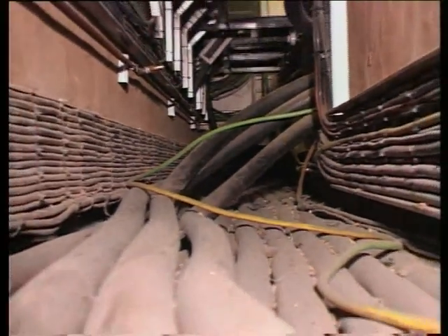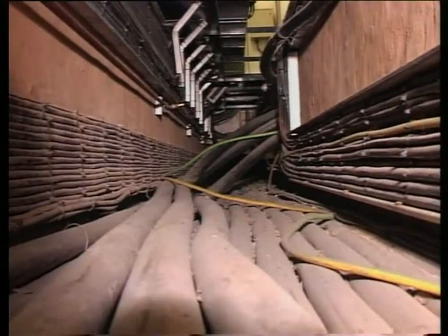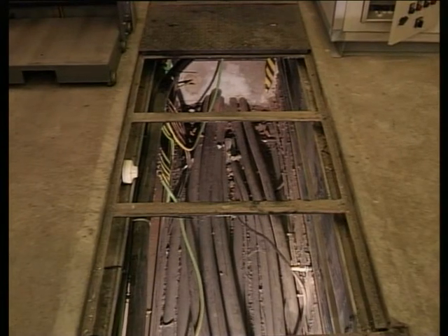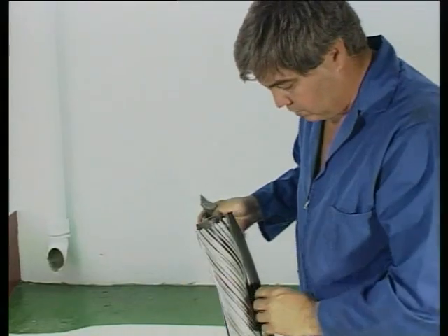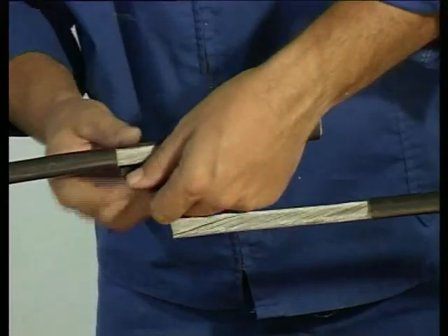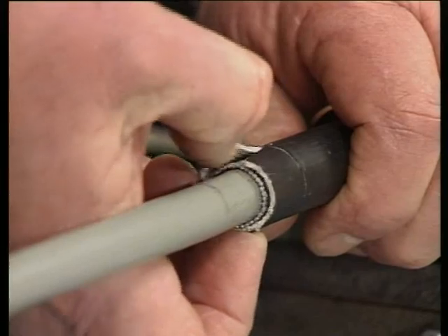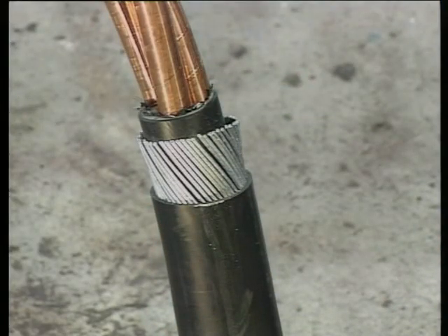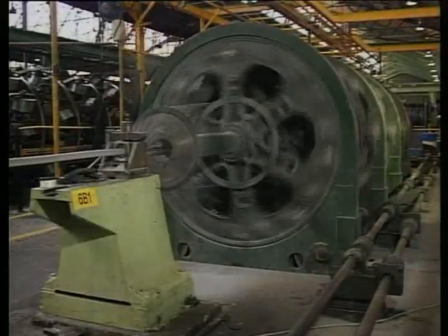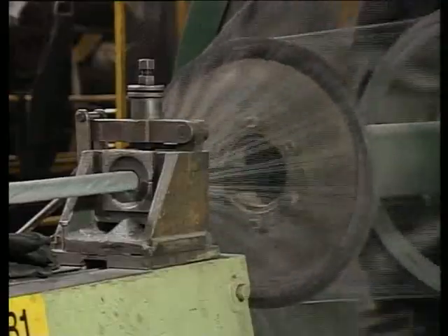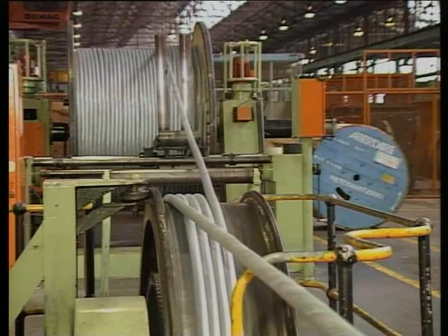Let's move on now to describe other aspects of cables which you'll need to know about when you come to perform such tasks as jointing or terminating. Many cables that you'll encounter will be of the armored type. An armored cable is capable of withstanding mechanical loads, such as the crushing load imposed when it is buried under a meter or so of soil. A common method of armoring is for the manufacturer to wind or lay galvanized steel wires upon the bedding, thereby creating a strong, crush-proof layer.